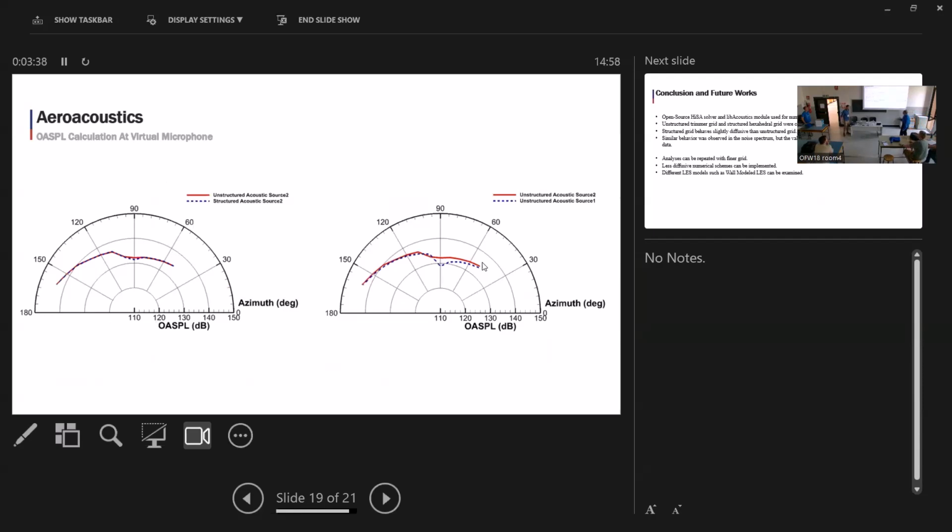I also wonder, you're using density-based? Yes. Why did you choose density-based, if not pressure-based? That's going to give you totally different results. In OpenFOAM, there is no density-based coupled solver, and we just tried an implicit density-based solver. We tried it and compared the results. Also in OpenFOAM, pressure-based solvers are segregated, so delta T decreases and the computational time is dramatically increased compared to a coupled solver. Right, so the density one gives you better results. Okay, that's very good to know. Thank you.